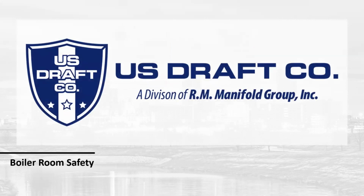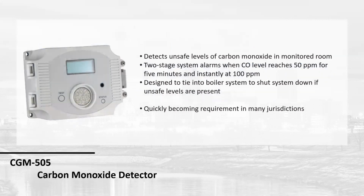Finally, boiler room safety. This is something we have been spearheading across the country, and that's carbon monoxide detection. The state of Texas recently implemented a rule where every mechanical room requires a CO monitor that interlocks with the appliances. And if you know anything about Texas and California boiler codes, they like to kind of piggyback off of each other. As soon as one does something, the other one does it, tries to beat it. Very competitive in that regard. So I would not be surprised if California requires it here in the coming years. It might even become a national code.